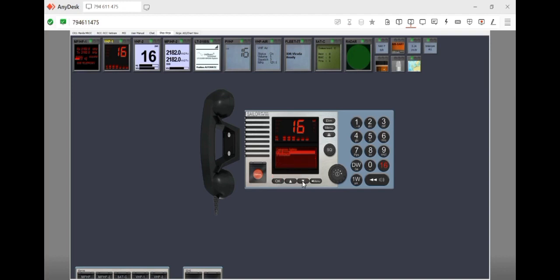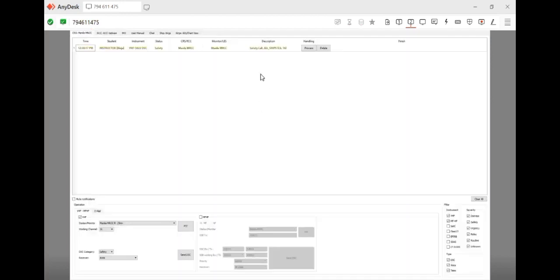You may choose all ship or individual. This time choose all ship, press OK, then again enter working channel, for example 16, press OK to accept, then OK again to transmit. To check, the instructor will go into the monitor of the coast rescue station to see if your safety alert was transmitted.